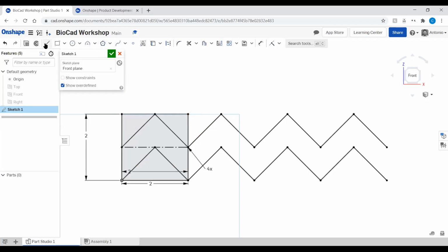So what we're going to do is click this line over here, and then I'm going to find the bottom left-hand corner of this box and come down a little bit. You can go up or down an arbitrary amount. Then I'm going to click and drag it left. If you aren't sure that you're hitting exactly horizontal, just get close to where you think horizontal is, and it should snap to it right there. So I'm going to click it right there and then hit escape to get rid of it. So there we've got an unconstrained blue line floating out in space.